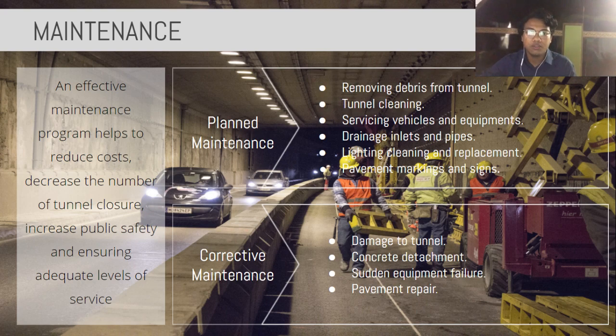Next point is servicing vehicles and equipment. Vehicles and equipment should be serviced to ensure readiness and performance. When servicing vehicles, the engine and motors should be checked for things such as appropriate fluid levels, unusual sounds, excessive temperatures, and any vibrations. The example of vehicles and equipment are the emergency response vehicle or first responder vehicle.